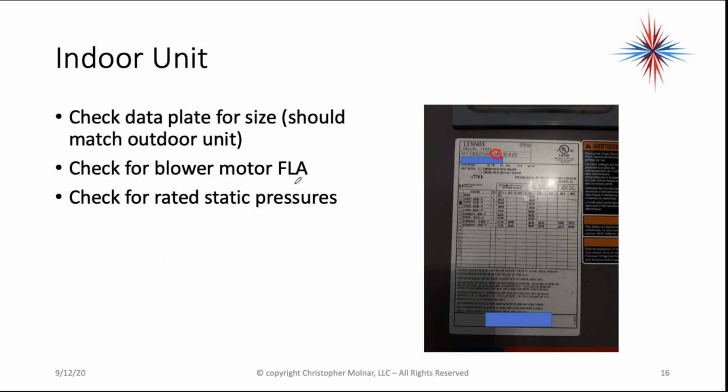Check for the blower motor FLA or RLA. It's on here someplace. In this case, it's 4.1. It's listed right there. Check for rated static pressures. When we look at this, there's a static pressure reading on here someplace, and it's going to be a 0.4.